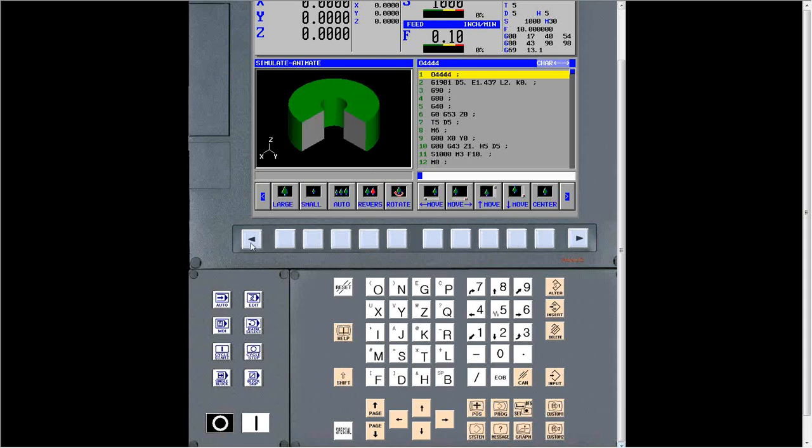So see now the cutouts where we can see it. And that's what's good about the rotation. You can get the blank to look however you want it to look. When we press start, we see the tool go all the way through to make one rotation and then come back out. So that's type 1 thread milling.